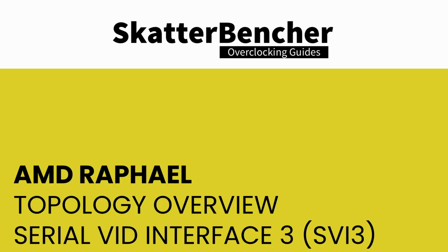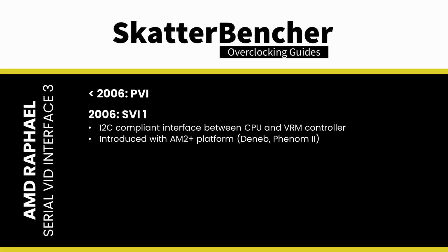AM5 Raphael desktop CPUs support the brand new SVI3 interface. SVI stands for Serial VID Interface, and it's an AMD designed technology or interface that facilitates communication between the CPU and the voltage regulators. AMD introduced the first generation SVI to NDA partners in January 2006 as the successor to its PVI technology. It was introduced to the market with socket AM2 Plus processors about 1 year later.